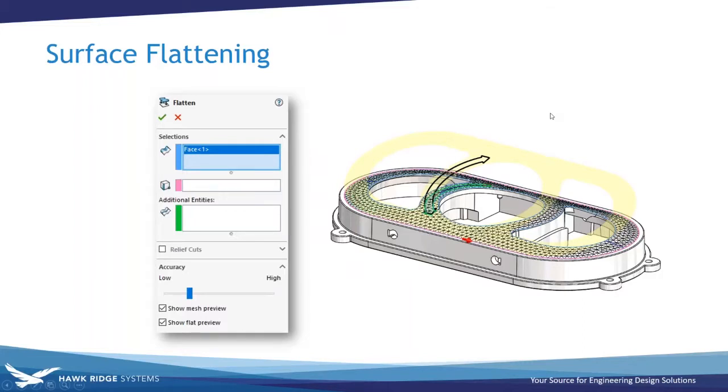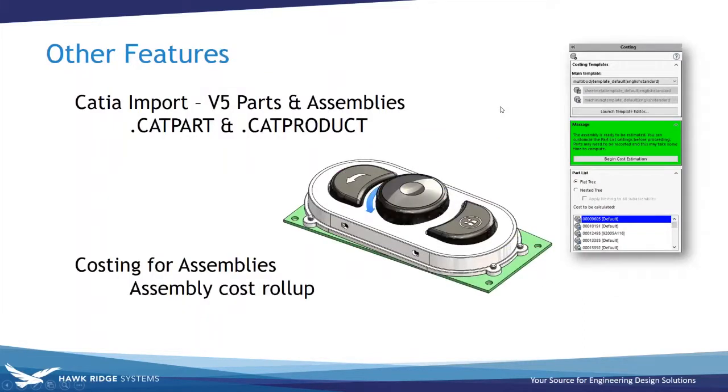A couple last features to talk about. These are smaller or more, again, niche ones. CATIA import functionality. So with SOLIDWORKS 2017, they introduced a new import engine called 3D Interconnect that allows us to import other CAD software files like Inventor files, Creo files. You can pull those in directly. They also enabled the capability to import CATIA files, but only for SOLIDWORKS Premium. So it's a little bit of another perk of having SOLIDWORKS Premium there.